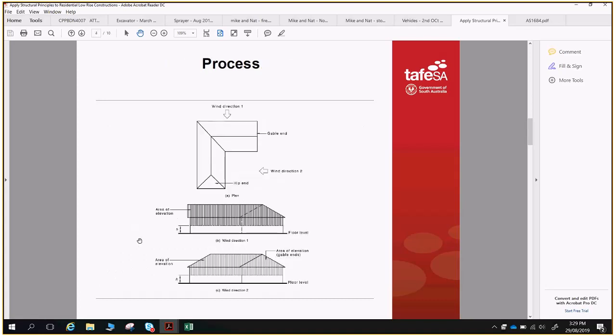Bracing does get a little bit tricky, in that there are certainly many little aspects that are unique to each type of bracing. I won't be poring through it in that sort of detail. I do suggest you sit down with this for a decent amount of time at some point. Maybe get a copy of AS 1684 and read it from front to back, but spend some time on the bracing and look at each of the clauses carefully. I'll be giving you an overview of it and then how it can be applied to our project.